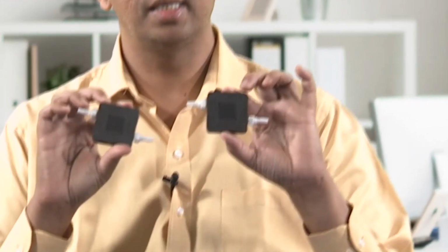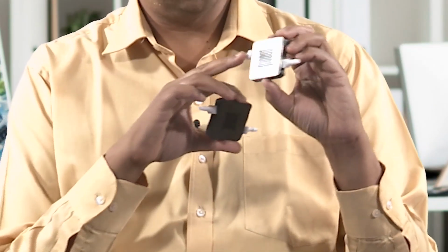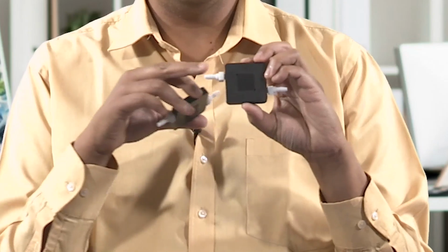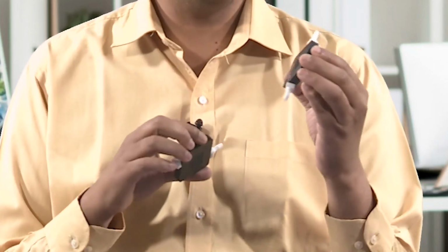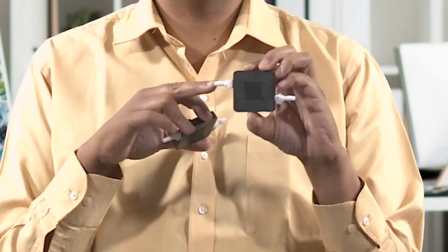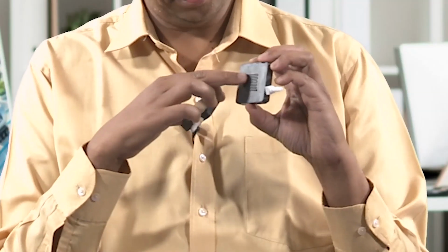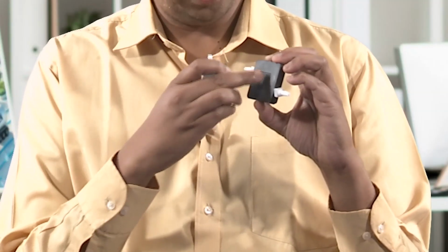So what we have here is the monopolar plate. These are the monopolar plates. When it comes to a stack, they become bipolar plates. We have these channels on both sides, which basically take the fuel. This plate happens to be on the hydrogen side. The hydrogen can be supplied from this inlet. Once it enters these channels, we have the diffusion layer right here, and then the gas diffuses and reaches the catalyst for the hydrogen side.